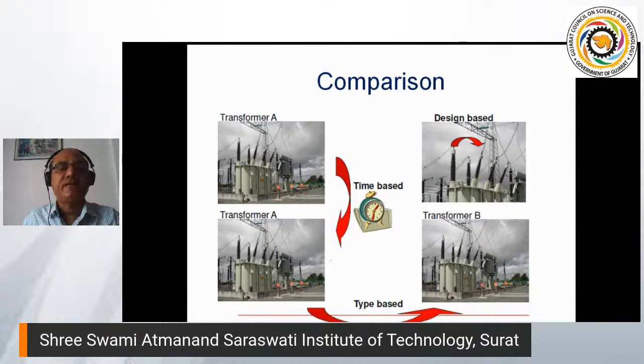After some time, again the frequency response of transformer A is measured, and these two are compared. If these are the same, so initially it has been done, say, at the time of installation at the new stage, and this is done after periodic times, after 1 year, after 6 months, whatever is decided. So that is a time-based comparison.